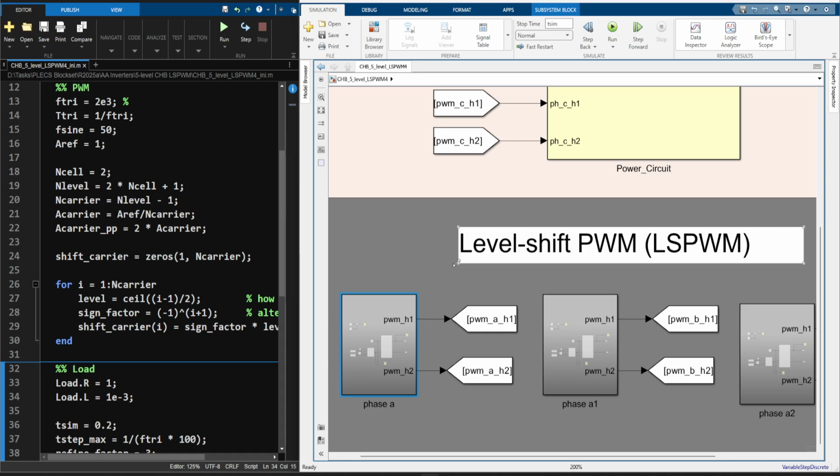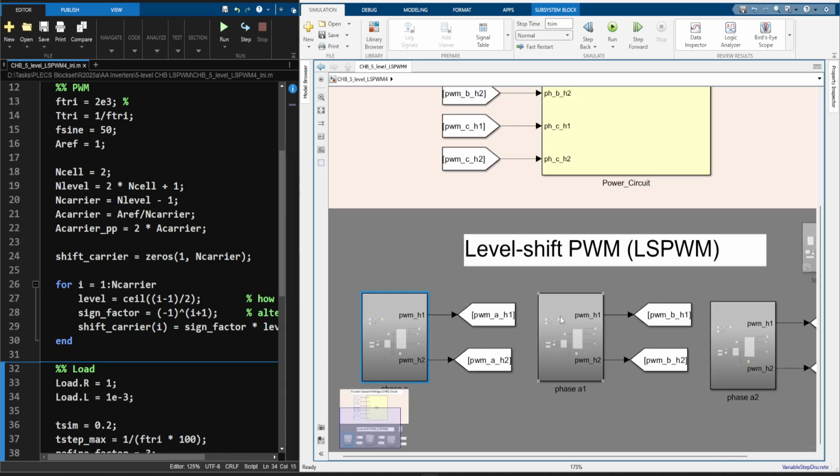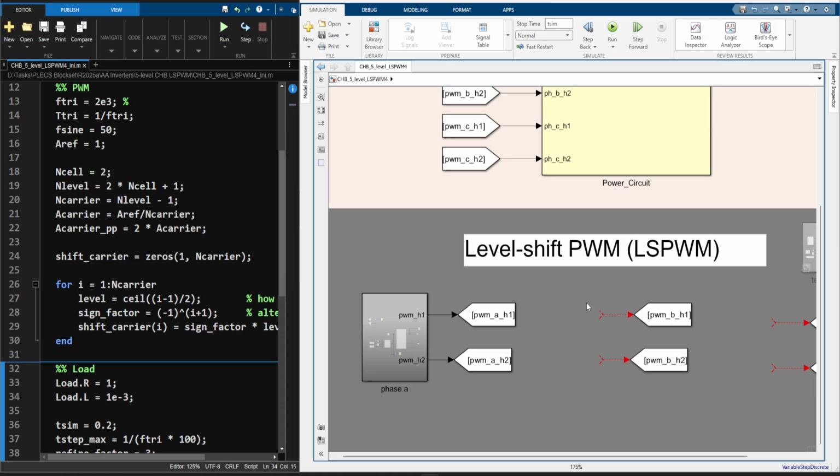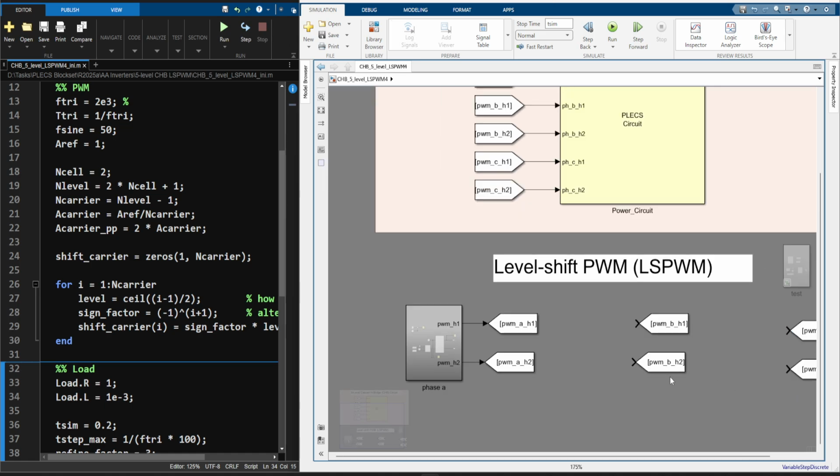As I mentioned before, I took it separately because I wanted to have my file structure organized so that I can follow it in an easier way. Now, say for example, I want to get rid of the redundant 2 blocks and want to integrate the implementation of the 12 pulse width modulated signals into one. To do that, let's get rid of these two. I will keep the go-to file since we'll need it from this block as well.